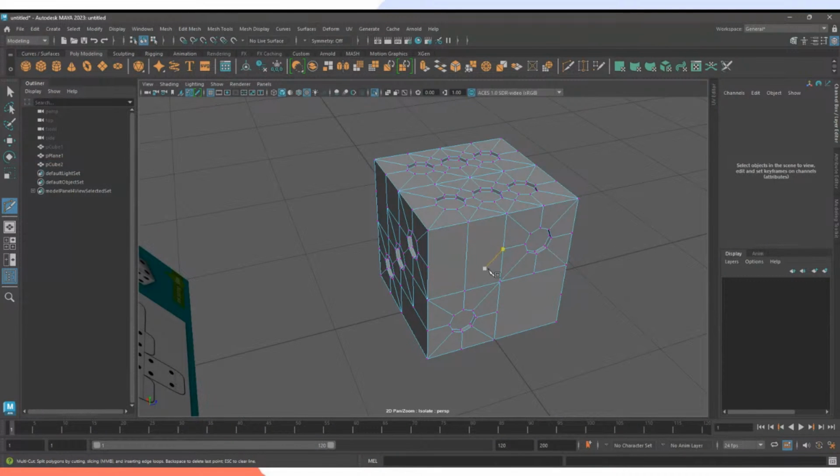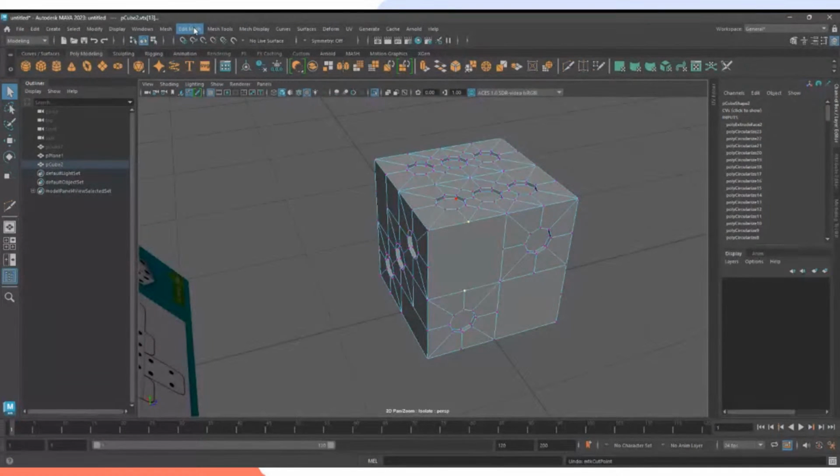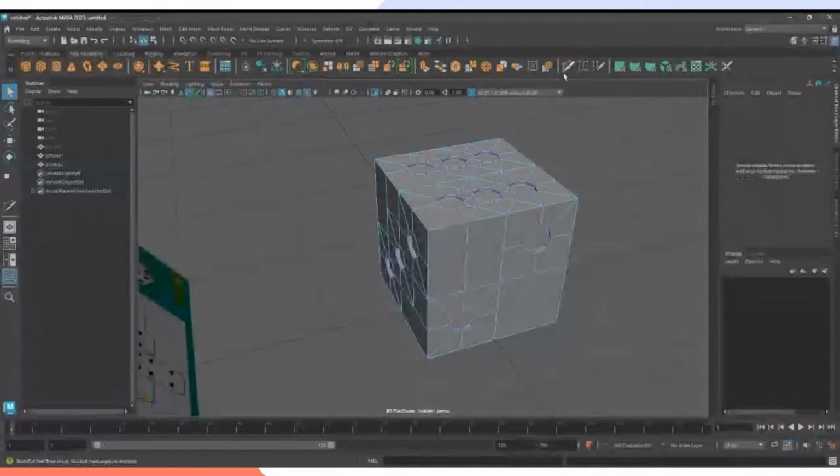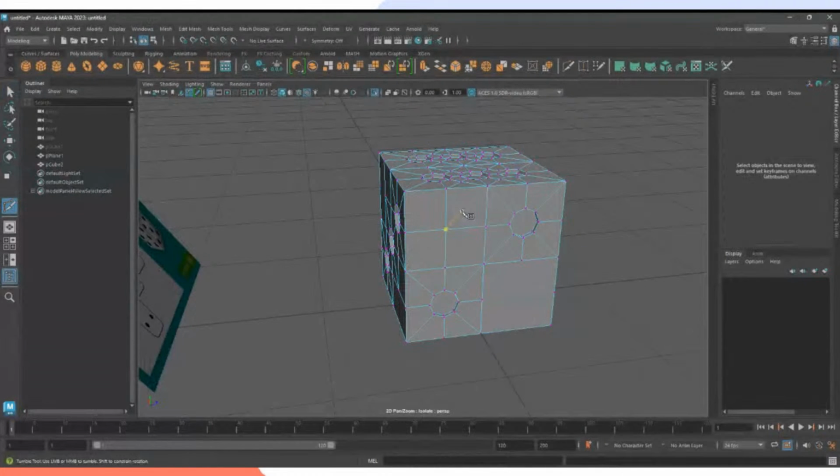Now, this is just 6 sides, but there's another way. If it's useful, go to Edit Mesh and press Connect. It does that immediately. I don't think this will work if there's already a... No, it doesn't work. There's already a line here, so it's best to just use the multicut tool. Shing! Now that's fixed. Now that's just 4 sides.